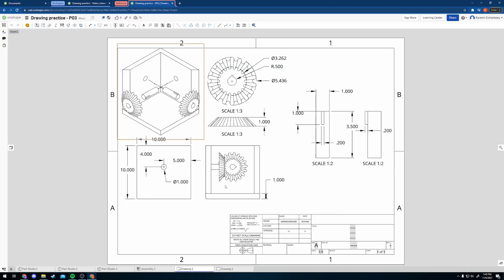So you can just export something like this, which, as you can see, shows dimensions of all your parts. It can show how everything fits together and the dimensions of the individual parts as well. This is incredibly useful, but one thing to realize is with each one of these views, you're trying to show a specific piece of information so that somebody can replicate this entirely. If I give them this image, they can recreate these parts. So you need to think about that when you're choosing your dimensions.